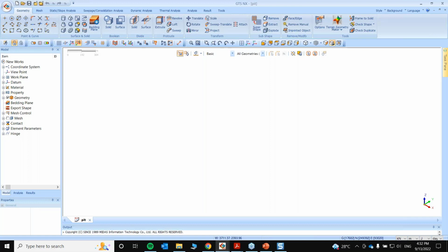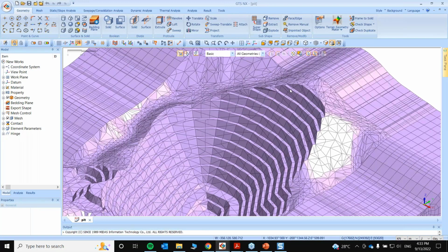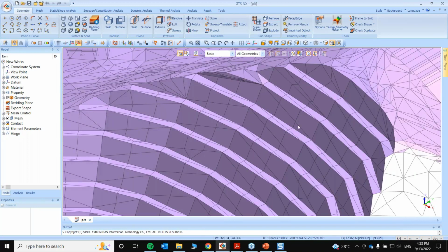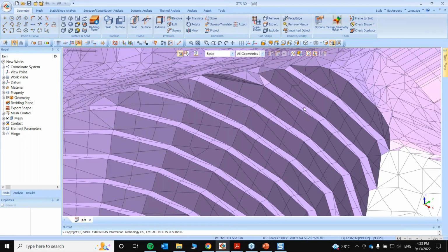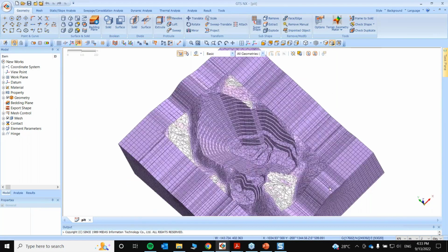Mr. Pritham, you need to remember this: your bench local slope angle, meaning the angle created between two adjacent benches, can be varied, and it normally varies in every mine based on the stiffness of rock at that point. That is why even in this particular mine, this face is concave shaped.